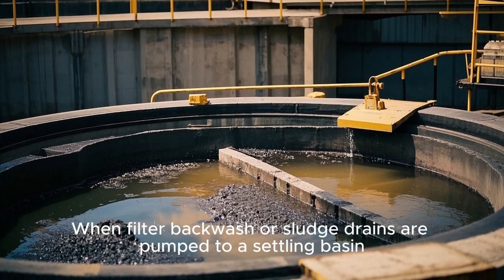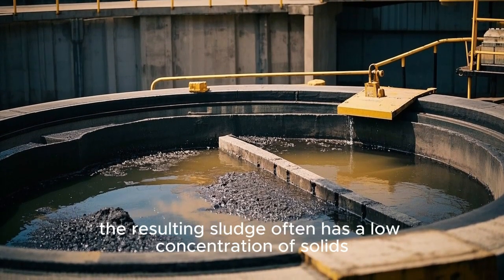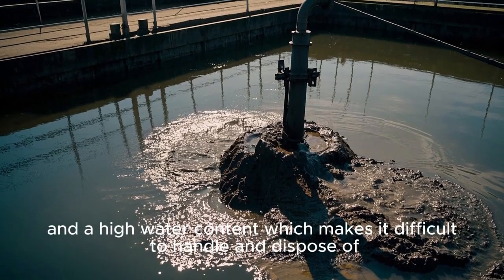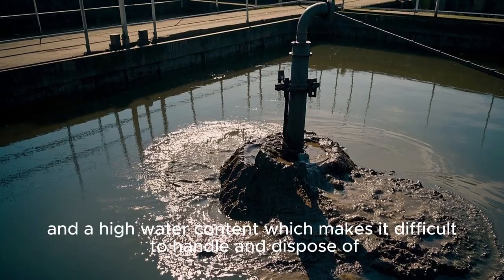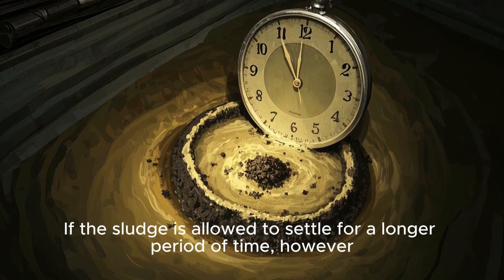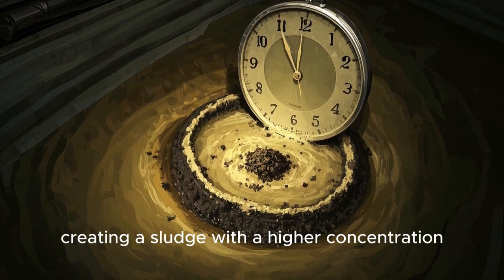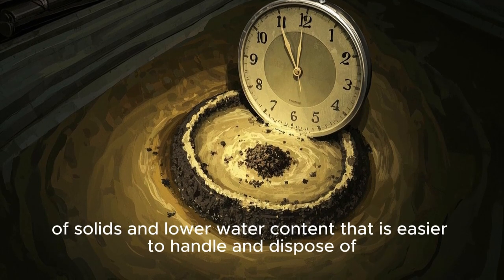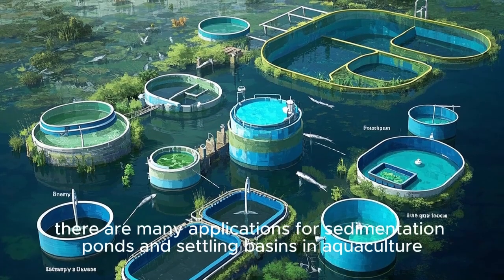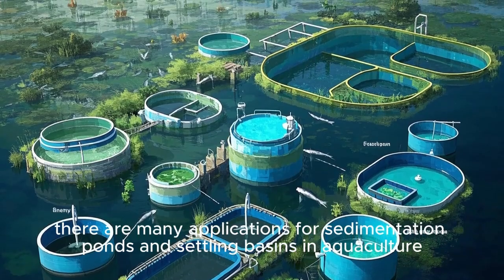When filter backwash or sludge drains are pumped to a settling basin, the resulting sludge often has a low concentration of solids and a high water content, which makes it difficult to handle and dispose of. If the sludge is allowed to settle for a longer period of time, however, the small particles will settle out, creating a sludge with a higher concentration of solids and lower water content that is easier to handle and dispose of. In summary, there are many applications for sedimentation ponds and settling basins in aquaculture.